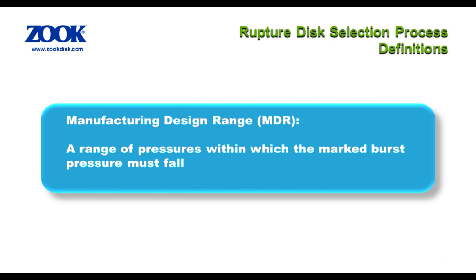In the case of metal disks, raw material is typically supplied in coil or sheet form. Two separate heats of material will never be exactly the same. Even within an individual coil, the left side could be microscopically thinner than the right, the start slightly different than the end. Seems insignificant, except when you're trying to fabricate a repeatable pressure relief device reliant on consistent tensile strength.